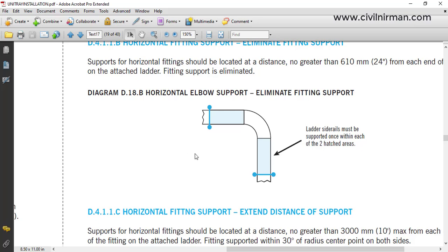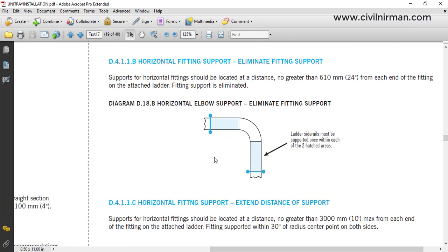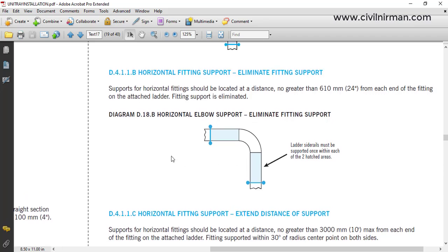So all this information will be available from the cable tray vendors, and you need to coordinate all this information with your electrical and instrumentation discipline. They will provide you the design data based on the vendor, once the vendor is finalized for your cable tray installation, and they will guide you further based on the details the supplier will provide. So this is one of the highlights from the cable tray inputs that you will require,